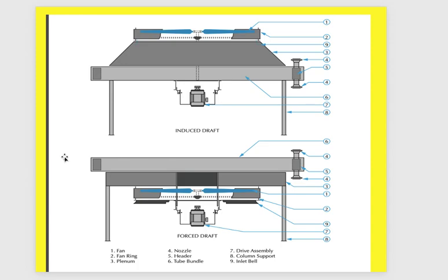Louver function is to protect rotating equipment and to control the airflow direction and prevent the foreign object entry. This louver controls the amount of air going through this plenum. Okay, if it is vertical, for example, it will pass 100% of the capability of the air cooler, and with angle you can control this louver.